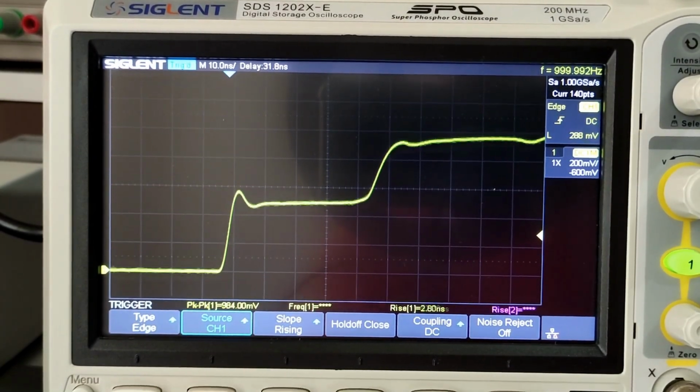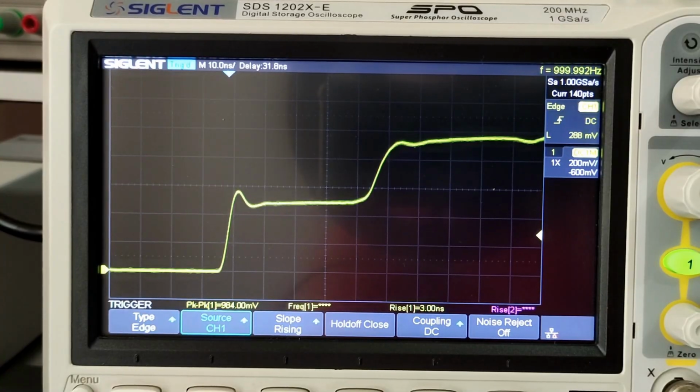This is how a step signal looks in a PCB trace. But why does it look like two steps instead of one? That is because I have made this trace intentionally long so it behaves like a transmission line and we can observe reflections. And this can ruin your day if you are not paying attention when designing your PCBs.